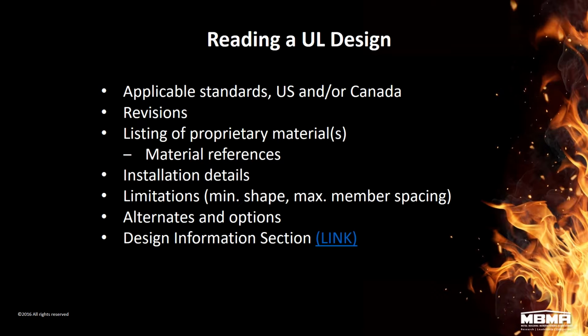The listings give you all of the requirements, both in terms of installation requirements, in terms of design limits on minimum sizes, spans, if you will, or spacing of members, as well as the brand names, the types of products, proprietary products that were tested and validated for use in that particular assembly. Any alternatives, alternates, and options that are approved are also given.